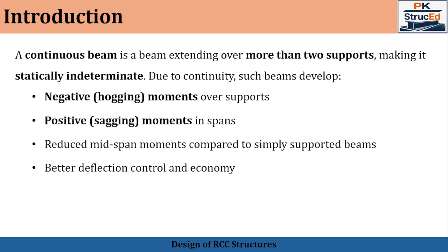So what is the importance of the continuous beam? In real structures, beams are rarely isolated. They are a part of a continuous framing system. These continuous beams tend to reduce the bending stresses, improve the stiffness, and provide redundancy and safety, whereas they require careful detailing and proper placement of negative reinforcement over the supports.